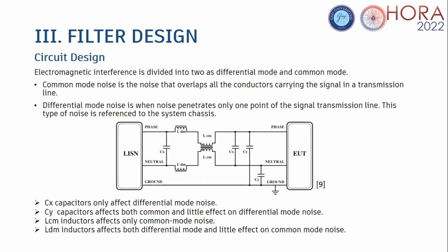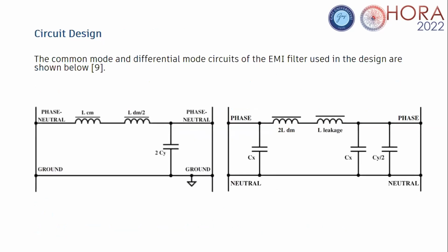And here are the CX, CY, LCM, and LDM components. CX capacitors only affect differential mode noise. CY capacitors affect both, but have little effect on differential mode noise. LCM inductors affect only common mode noise. LDM inductors affect both modes, but have little effect on common mode noise. The common mode and differential mode circuits of the EMI filter used in this design are shown below. The left one is the common mode circuit, and the right one is the differential mode circuit.